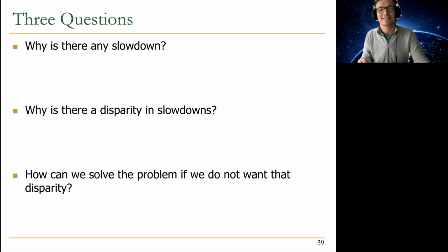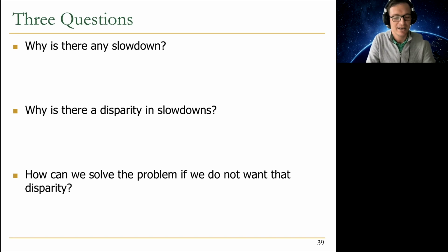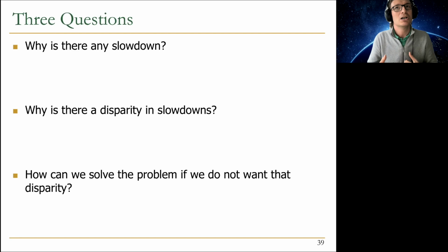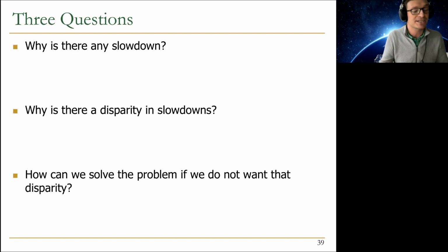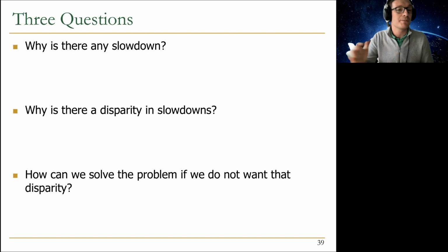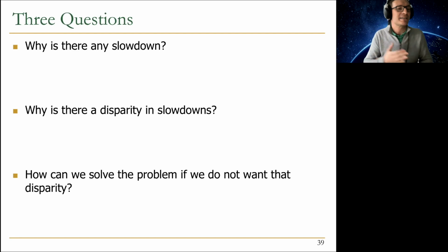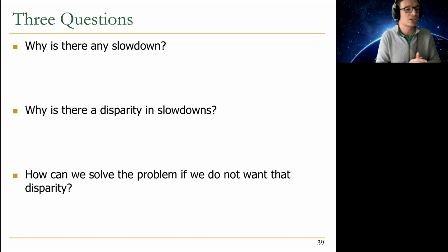So modern systems, what they do is when they figure out that the system is getting close to a thermal emergency, let's say, if it's running at a temperature that is considered too high, that it would potentially break down the system, modern systems do automatic throttling of workloads, such that they slow the workloads, like slow the clock frequency and reduce the voltage of a core.